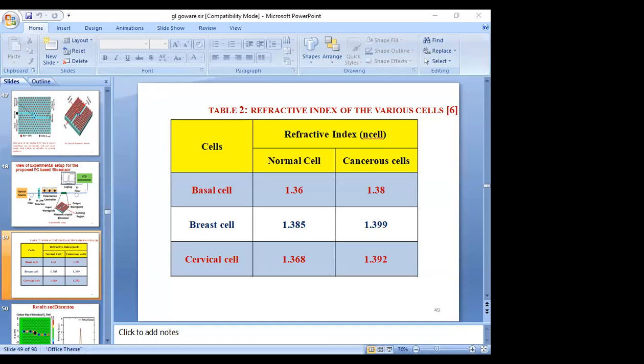You can see that there are some values shown in red. There is 768.5. What is that? Sensitivity. And then the shift in the wavelength is 211.19. Then sensitivity is 15,085. Figure of merit is 159. Here sensitivity is 6024. And we can say that for a radius value of 106, we are getting the very best result.